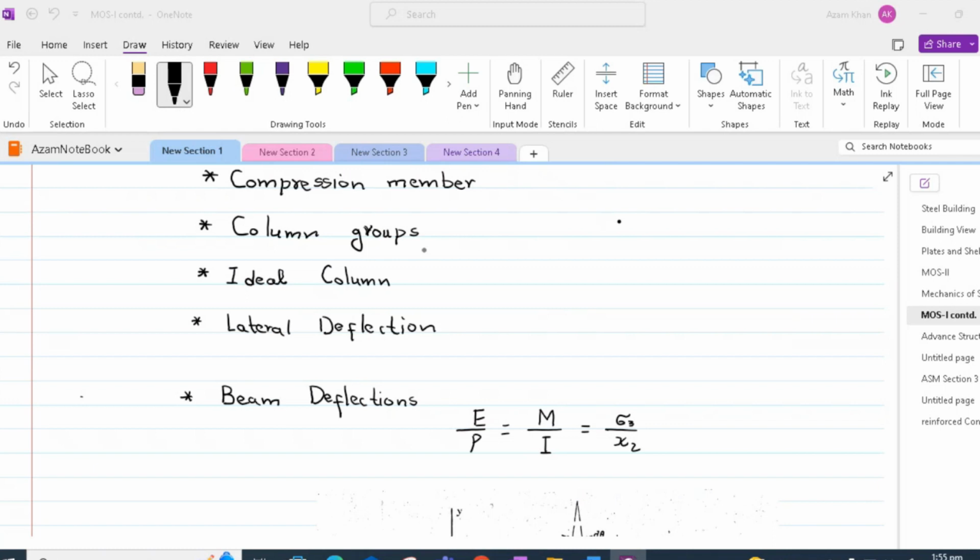An ideal column is assumed to be a homogeneous member of constant cross section that is initially straight and is subjected to axial compressive loads. Nevertheless, columns would have some small imperfections of material and fabrication irregularities, as well as unavoidable accidental eccentricities of loads.